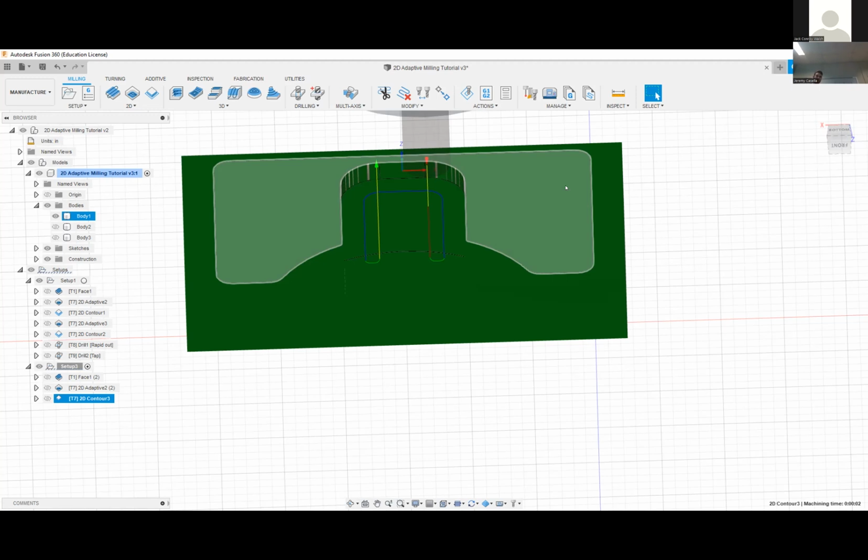When you design a part or you come on as a design engineer, you're often responsible for that part through its entire life cycle. That means it's your responsibility to sign off on non-conforming hardware. So the tighter you make a tolerance, and you'll learn about tolerances as you enter the workforce, I'm sad that they don't teach GD&T, which is a way of telling it, okay, I have this much I can go in each direction safely for a part dimension. But you'll have to sign off on hardware that's out of tolerance.